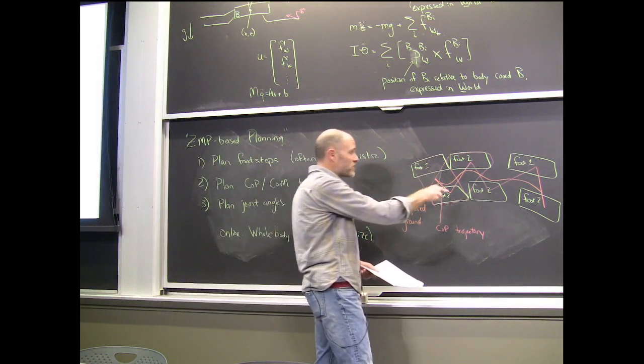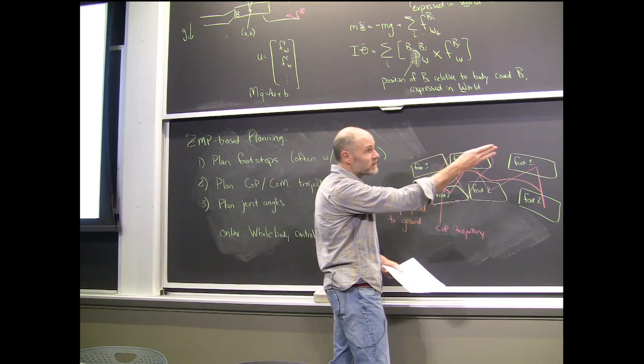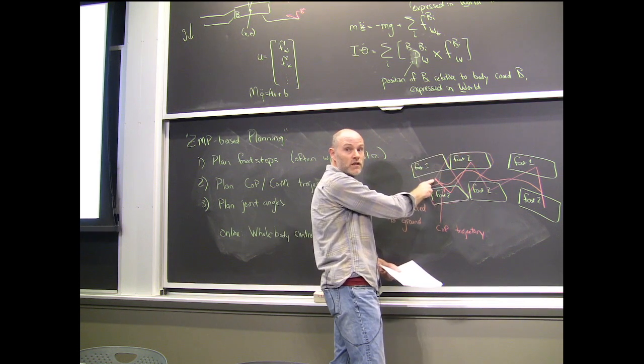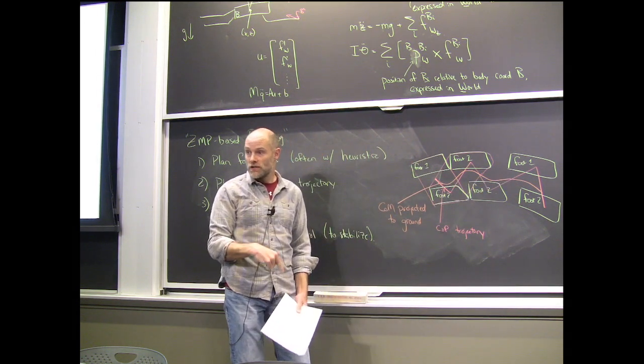Then these equations allow you to solve for that explicitly. You just integrate out. We have the relationship in terms of accelerations, but if you have the initial center of mass, you can just integrate the equations to figure out what the center of mass needs to do to make the ZMP trajectory happen.